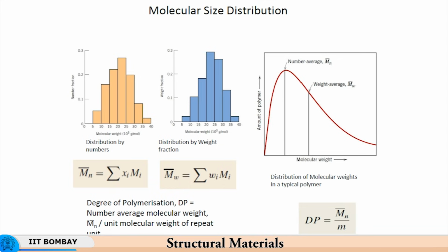So that is the difference between the kind of weights we talk about in case of metals as opposed to polymers, because in polymers you cannot consider atomic weight, you have to consider the molecular weight, because the molecule of the polymer is the one that governs the strength of the material, the structure of that particular molecule. So the structure at the molecular level governs the mechanical properties, the structural behavior of the material.